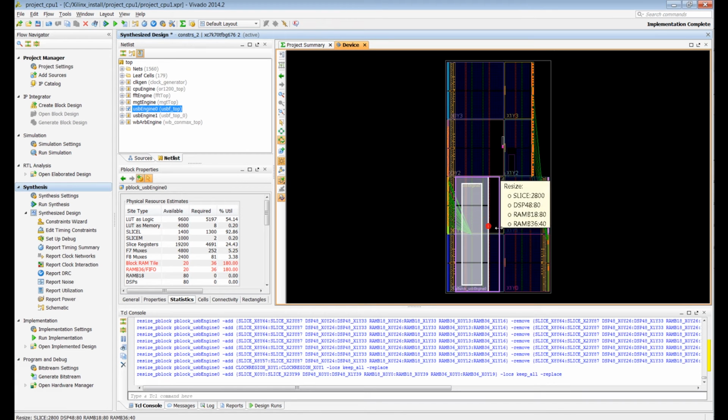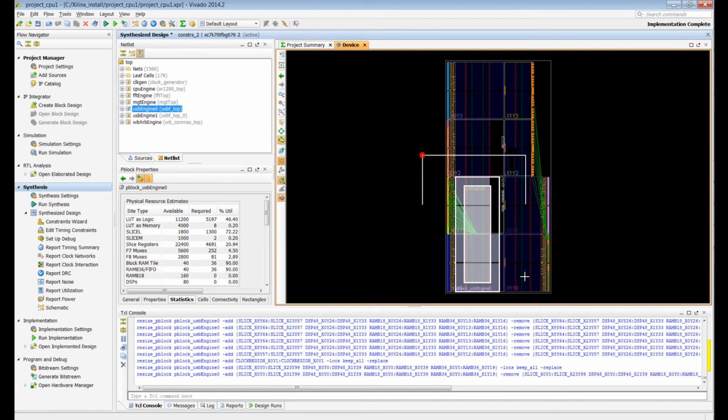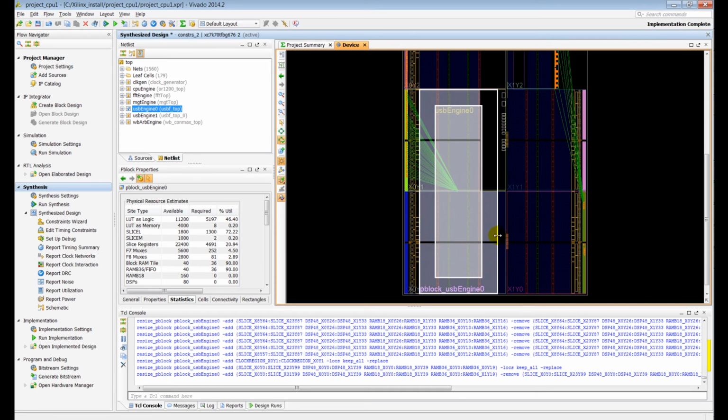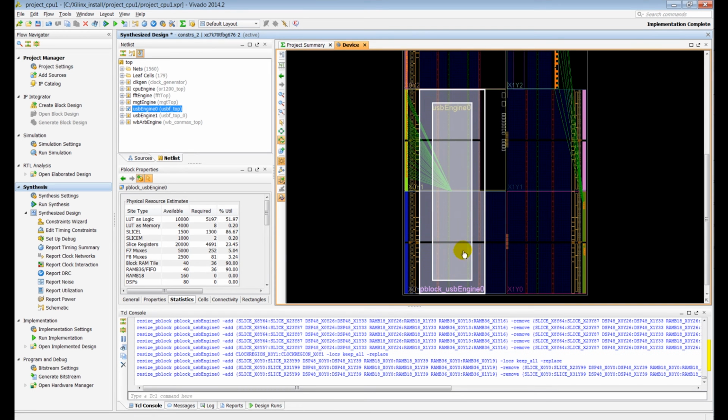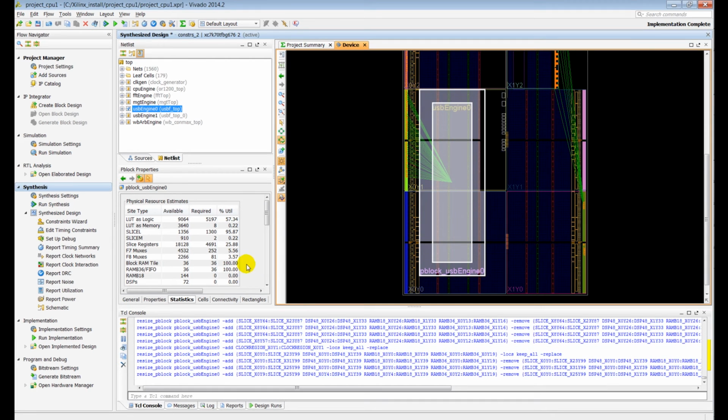Now here again, you've got some options. If you make the rectangle too small, in other words, the utilization too high for LUTs, for example, say 90, 95%, you are limiting the number of logic sites available for outside logic to also use. As you'll see in the implemented results in a moment, that space is available for other logic, and it's actually desired so that you can help to connect to the outside world, outside this pblock, and ensure timing is met.